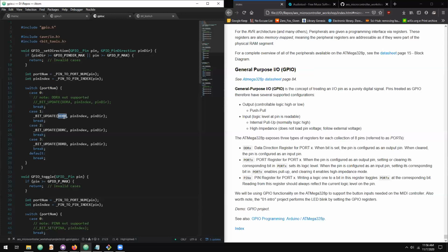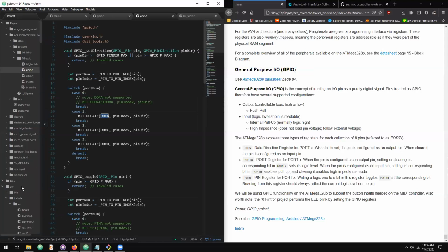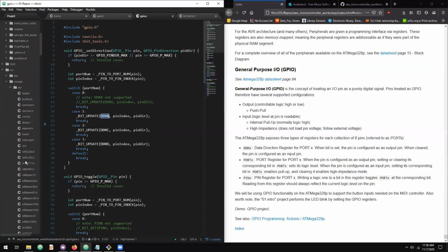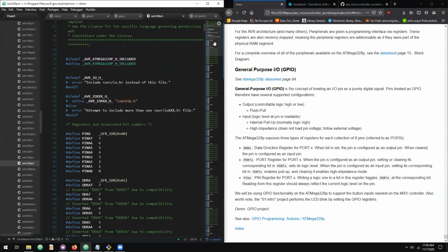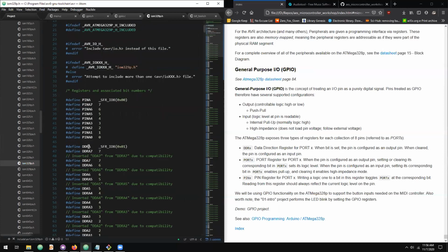And unfortunately, due to the way that AVR libc in avr/io.h defines DDRB, it's not a straight up memory address, it's a dereferenced memory address that we're actually accessing. And I can show you guys that real quick. So from avr/io.h, we're including this io, where's it, 328p file. So this defines all of the hardware registers as a helpful little technique.